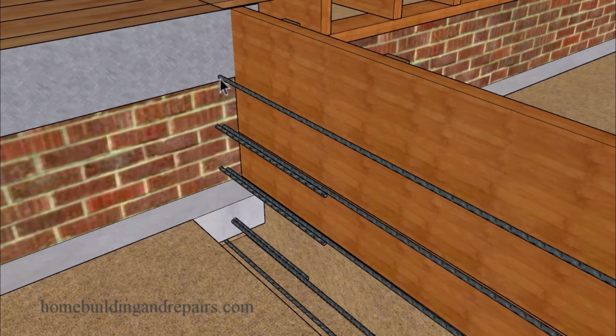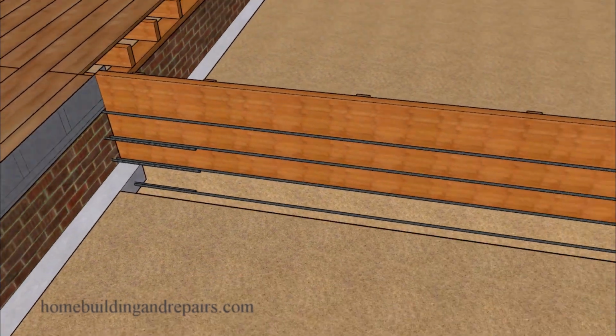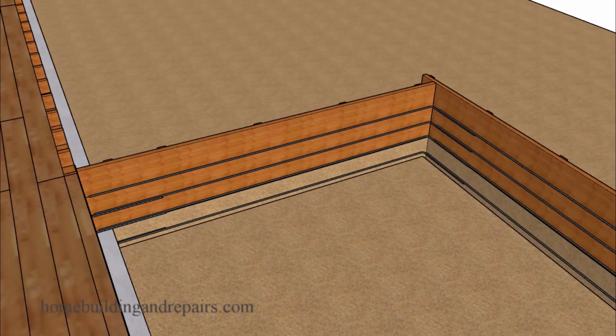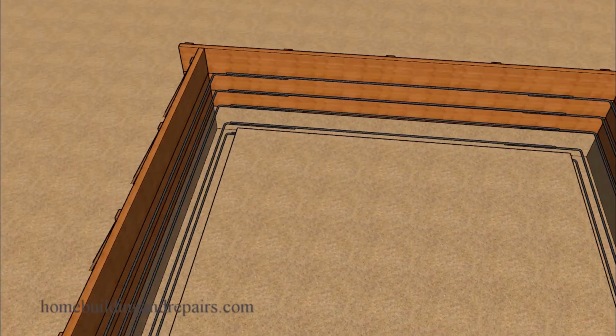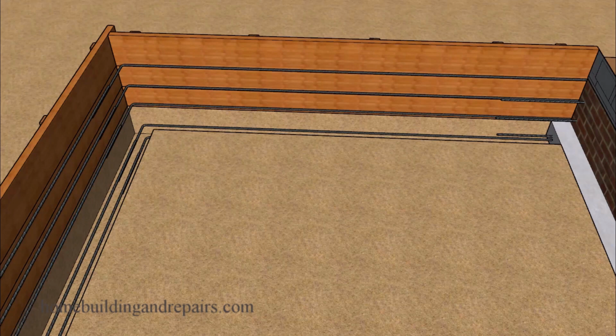So we're not going to have a dowel here. The rebar here wouldn't go into the concrete or the brick. And on this side of the wall, we're only going to be able to go in the thickness of the wall. And that might only be about 8 inches. And I really don't think an engineer is going to do that with a brick wall. If it's concrete, that's probably going to be a thumbs up on that one. But on brick, it might require something different.